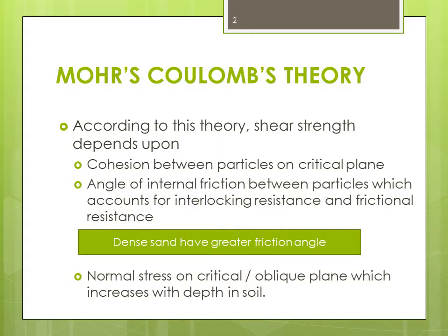Mohr-Coulomb's theory. According to this theory, shear strength depends upon the cohesion between particles on the critical plane, the angle of internal friction between particles, which accounts for interlocking resistance and frictional resistance, and the normal stress on the critical or oblique plane, which increases with the depth in soil. The important point is that dense sand has a greater friction angle.